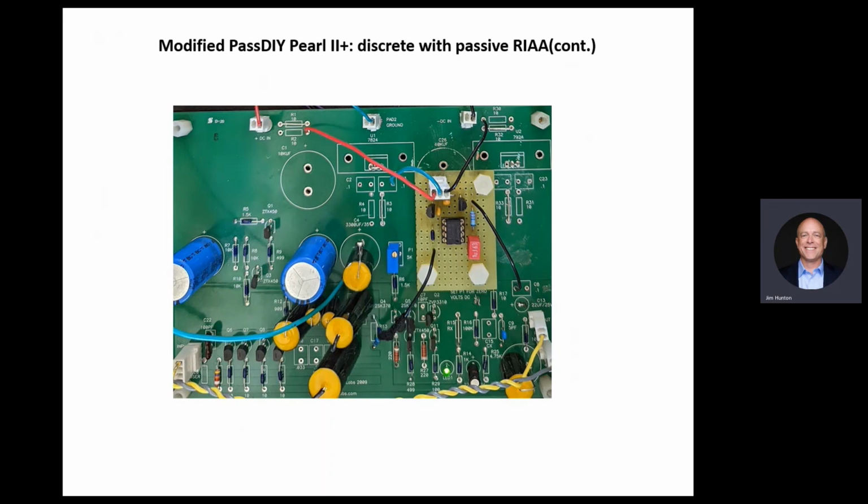And this is the servo which Jim built on a separate board. Now you would say, well, he does have a WIMA in there. Yes, but this is really not in the audio path, because there's a big cutoff at 0.5 hertz for that circuit. So you're not going to hear that. But when you put a DC servo in the output circuit, you're stiffening to some extent your bass. There's an effect on the bass response or the bass quality.